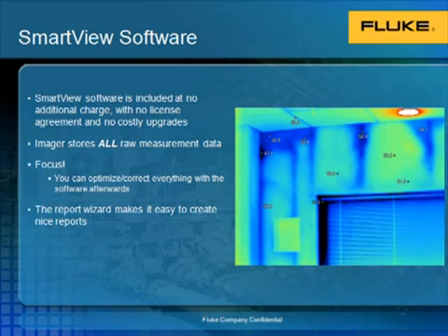Every point within an image carries temperature information and can be found either on the imager itself or in the software. I'd also like to stress the importance of focus. As long as you have the focus correct when you capture the image, all kinds of corrections can be made after the fact in the software. SmartView also has a report wizard that makes it very easy to create nice professional looking reports.